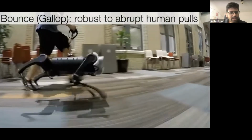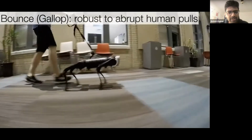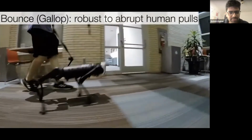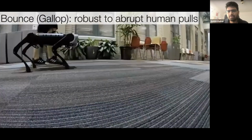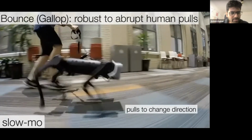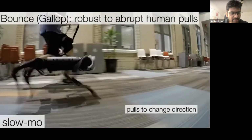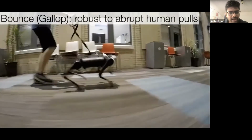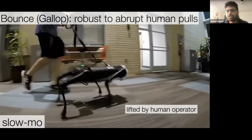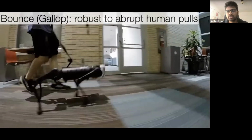We also abruptly pulled the robot to the left, and we lifted the robot and tried disturbing it while it's walking at 1.5 meters per second, and we see that it maintains stability. Now let me just slow it down once. You see that the operator will pull it to the left, and then the robot recovers from that. And at the end, when we pull it up, it starts flailing its legs to get back on the ground. So now it's no longer using any notion of gait anymore.